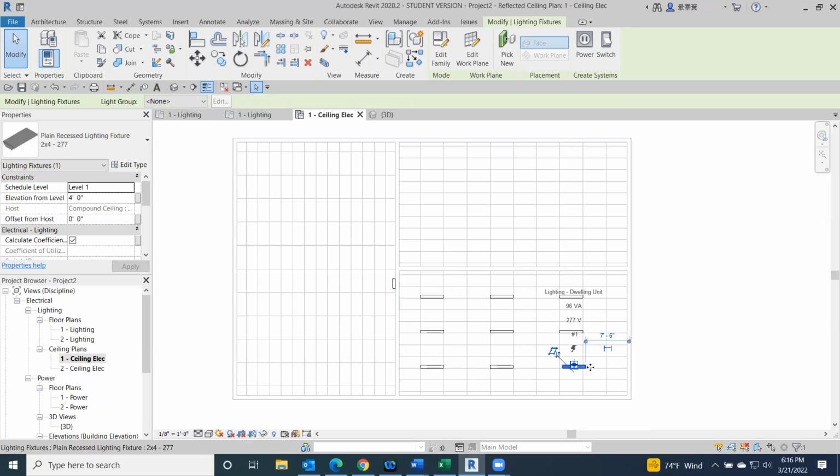And we want to make sure that we have all of our lights distributed evenly throughout the space. This is also a time where you want to think about the different type of light usage that you would have. If you have some spotlight needs, you can add the spotlights in there as well. This may be a time that if you're using multiple types of lighting fixtures, you put the two different types of lighting fixtures on separate circuits and separate switches.